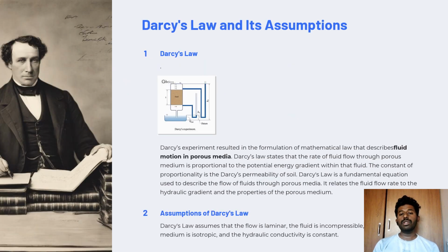So what is Darcy's law and its applications? Darcy's experiment resulted in the formulation of a mathematical law that describes fluid motion in porous media. Darcy's law states that the rate of flow through a porous medium is proportional to the potential energy gradient within that fluid. The constant of proportionality is the Darcy's permeability of soil. Darcy's law is a fundamental equation used to describe the flow of fluids through porous media. It relates the fluid flow rate to the hydraulic gradient and the properties of the porous medium.